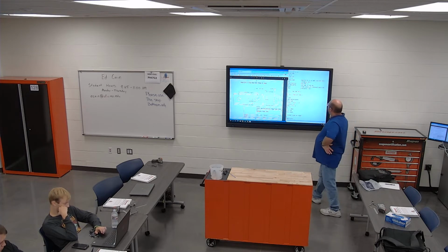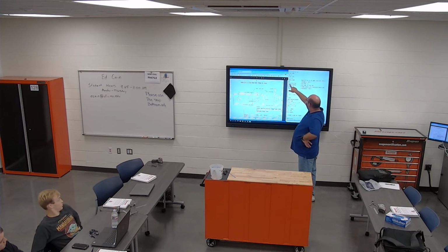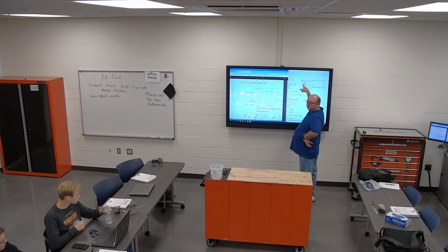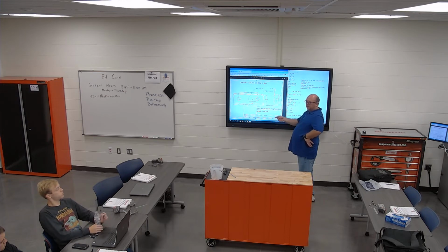So then, let's see, before he came in here, we were at G0 rapid move up to an inch, coolant off, M5, spindle off. G91, G28, Z0, that takes the Z to the home position. You don't necessarily have to put an X and Y in here, because if you put an X in here, it slides all the way up to the corner.